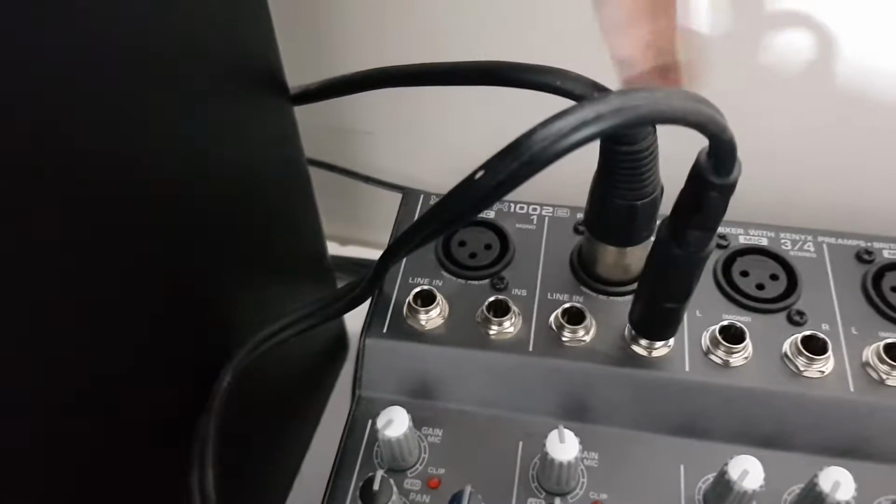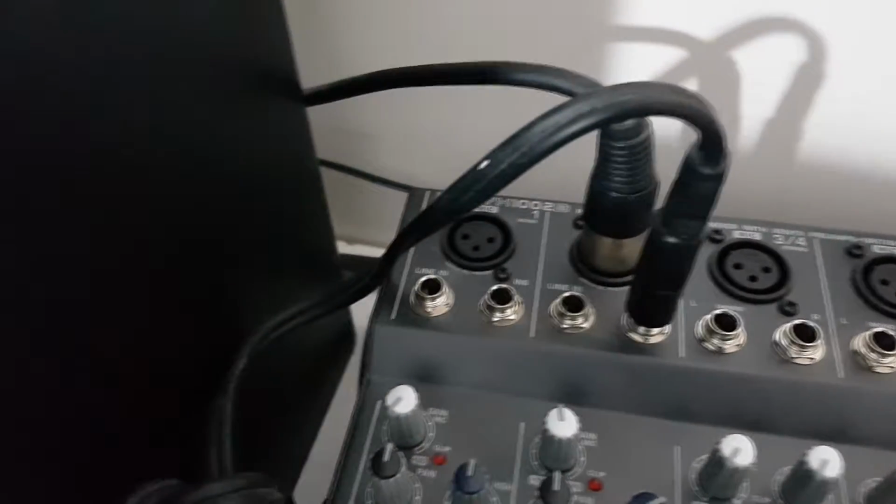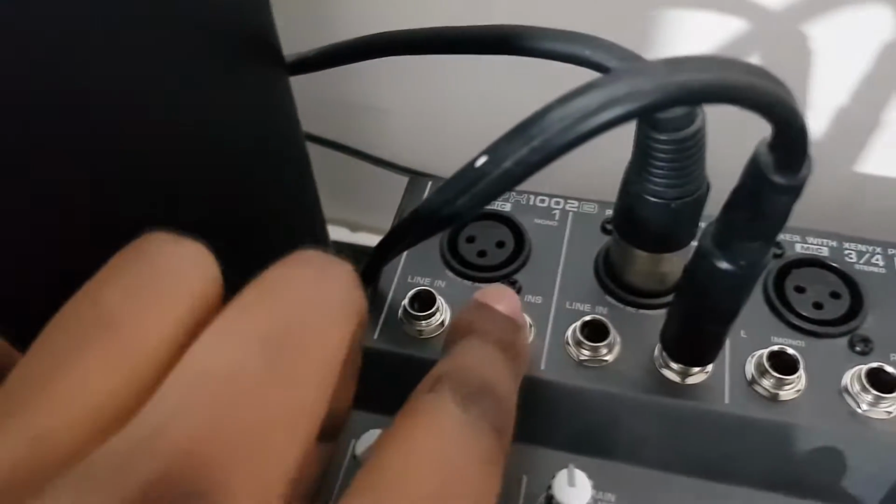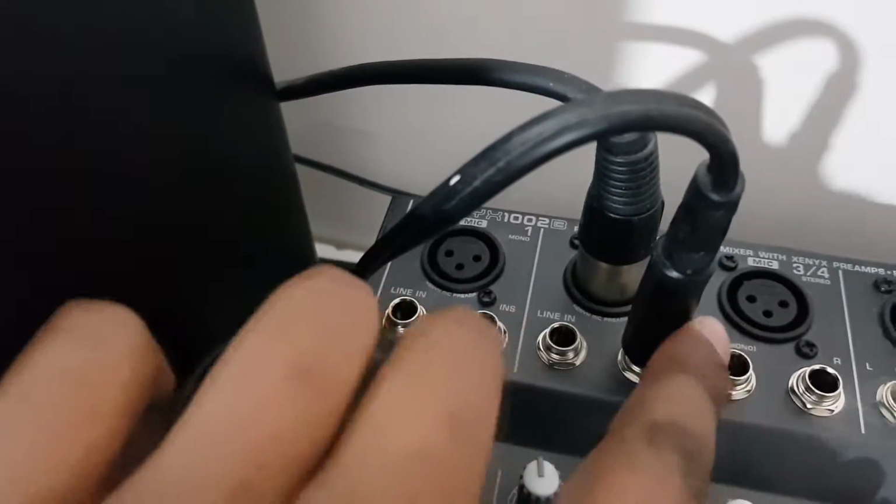Now the mixer that I use, as you can see, my microphone's plugged into one of my XLR inputs on my mixer. You're also going to need insert ports. The insert port basically lets you connect the compressor. I'll explain again in a little while how to connect it and why you need an insert port. It's important that you have an insert port if you are planning on connecting the compressor, otherwise you can't connect the compressor at all. So I have two insert ports on my mixer, and they work great.